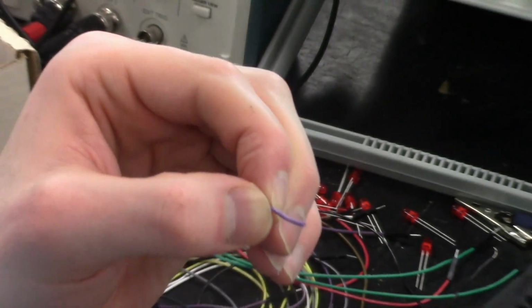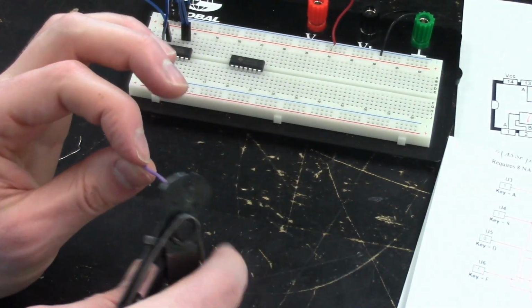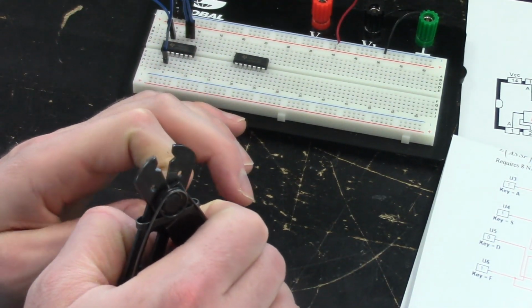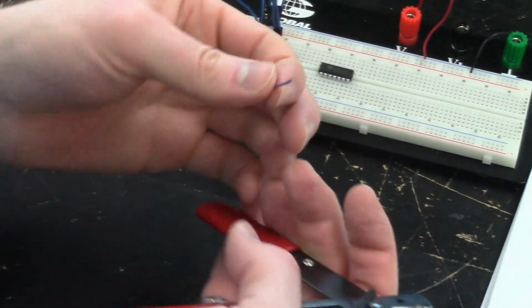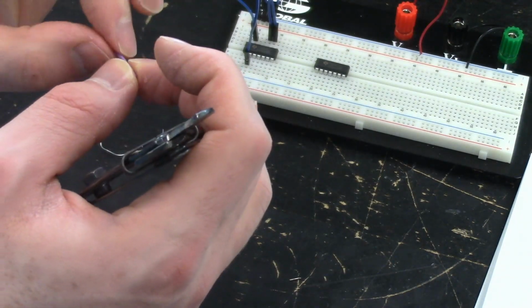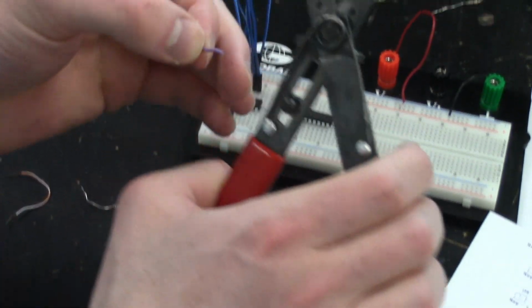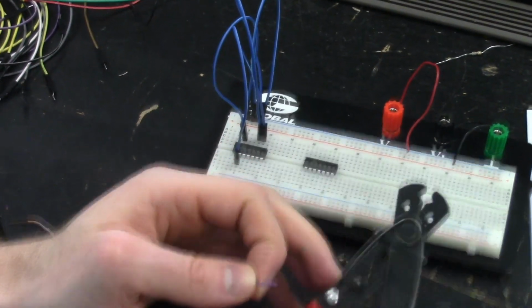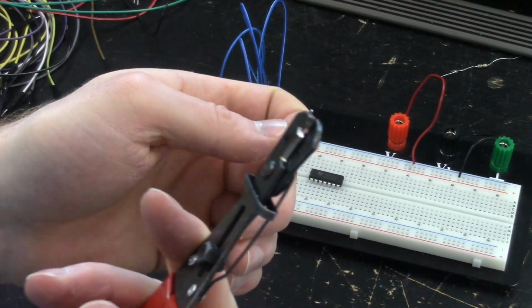Okay, well, we'll see if we can find some better wire strippers. If you find it's not actually reaching and cutting through the shield for the wire strippers that you have and the wire that you have, then the best bet is to just go and get a different set of wire strippers. So this one here is more flexible in a way, but it's a little bit trickier to use. Basically, you can clamp all the way down to almost nothing.